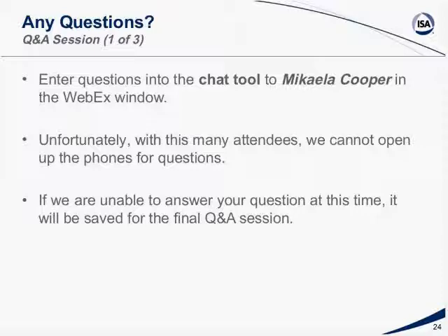Okay, next question from Daniel, and he asks, is there a need to differentiate between process alarms, i.e. for FDA compliance, and safety alarms, i.e. for personal safety? From a prioritization standpoint, they would be different alarm classes. You will set up alarm classes at your facility, and the ISA provides some guidance in 18.2 on how to do that. But from a prioritization standpoint, the prioritization would be the same.